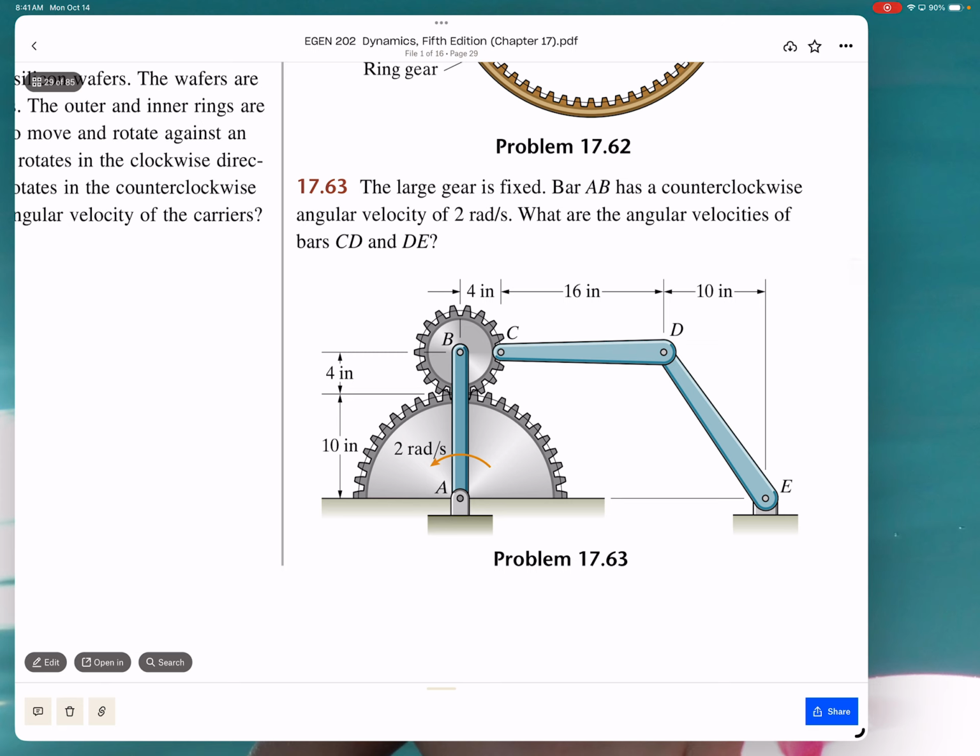That one ends up being a pain in the butt. Right? But then again, that process is: I'd start at E, and then I'd go to D, and then I'd go from D over to B, and then I'd go from B down to the point where those two touch. It's going to be 0 because that thing down at the bottom is 0, and I apply that constraint, and then it'll tell me omega of that one, and then once I get the omega of the big one, then I can figure out what the omega of the other one is.